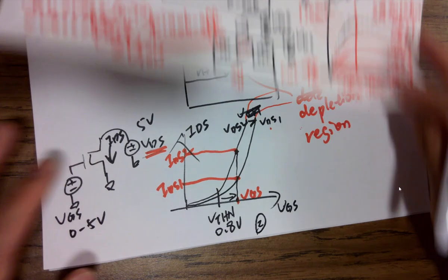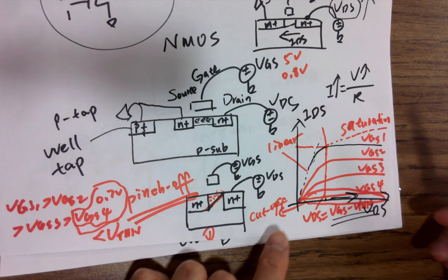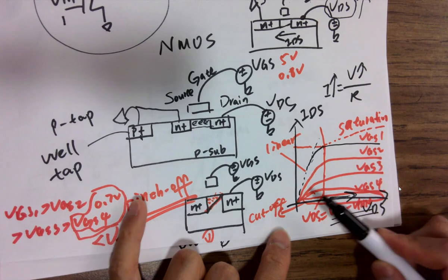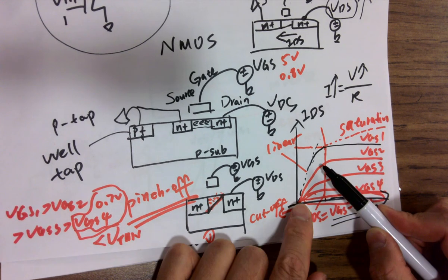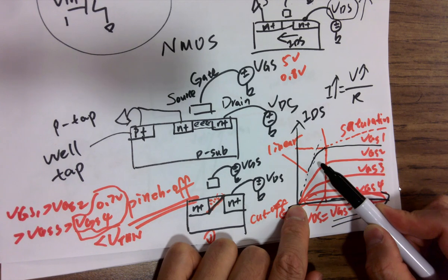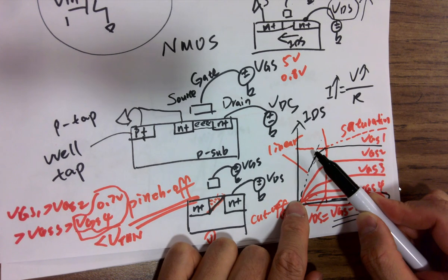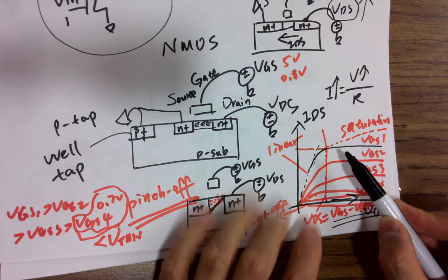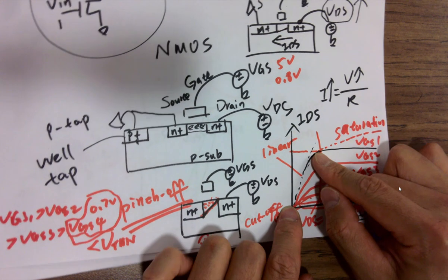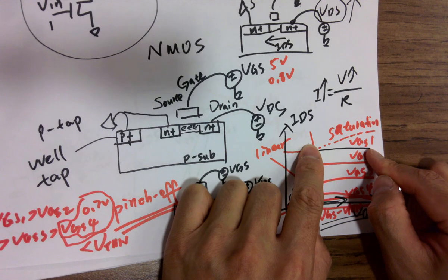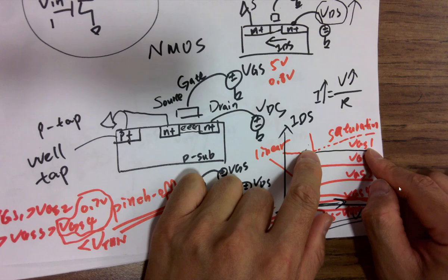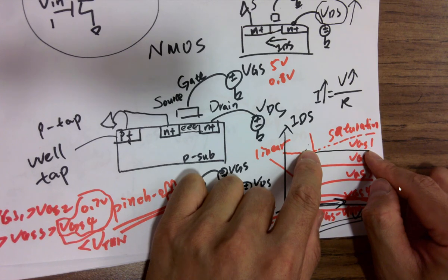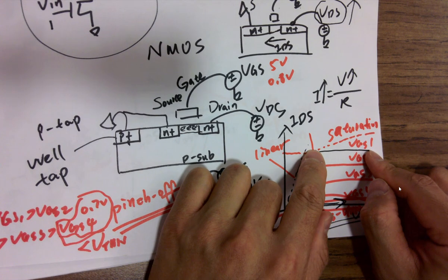Okay. So if you look at the VDS to IDS curve, there's VDS versus IDS, linear region. First, why is it called linear? Because it looks like a resistor. You get delta V divided by delta I as a pretty much constant value over here. So the question is, does this region have higher resistance or does this region have higher resistance? The saturation region has higher resistance, because increasing the voltage is not changing the current. It's like a super high resistor. So whenever it's operated in the saturation region, it's considered a current source.